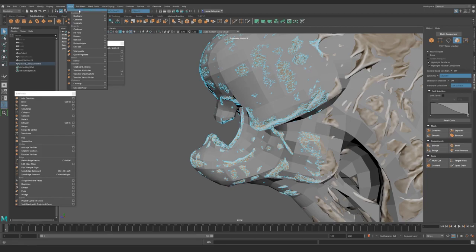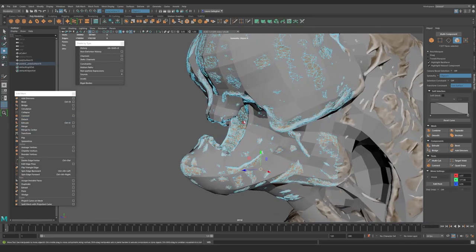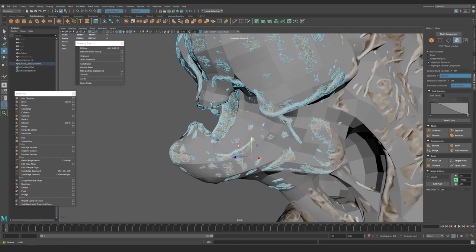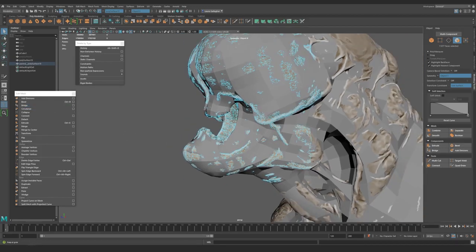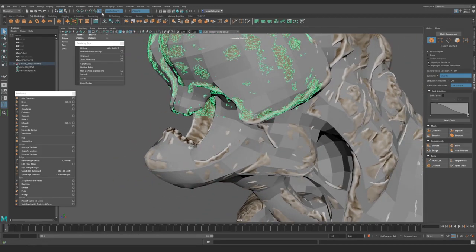And that is just to make my life easier as I'm working on the top gums of the character, because as we're rotating the camera around and moving those vertices around using Quad Draw, those vertices essentially snap to the surface based on screen space, based on what the screen is actually pointing to or has within the screen. Just here in this particular case, completely getting rid of the bottom of the jaw of the creature just makes it a bit easier to work on the top of the jaw of the creature.